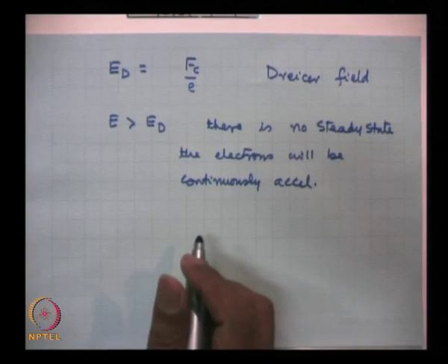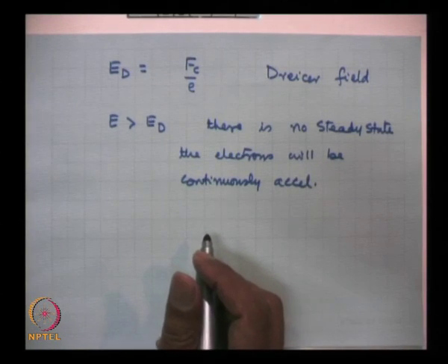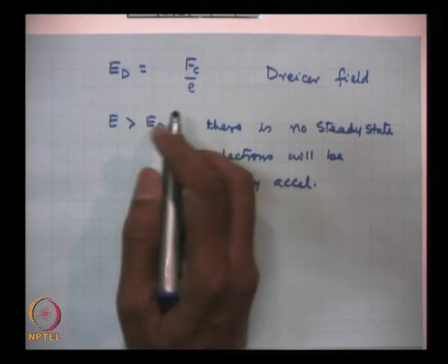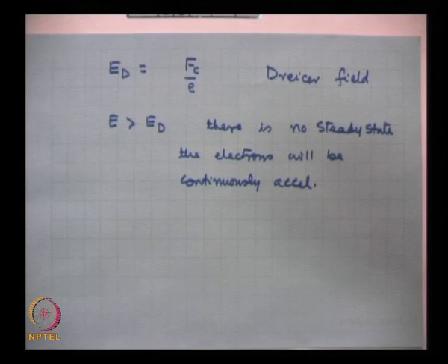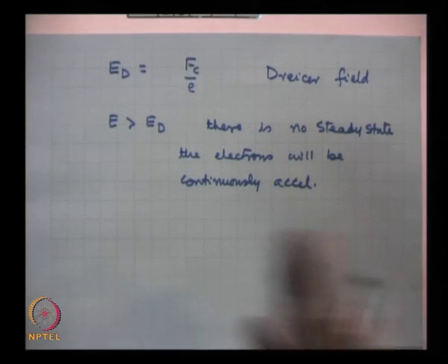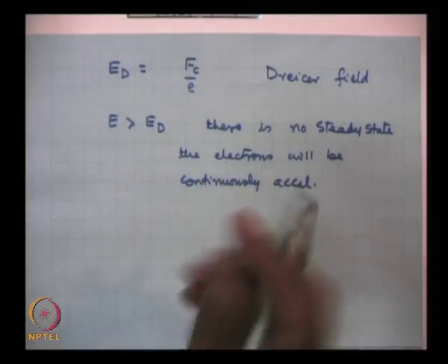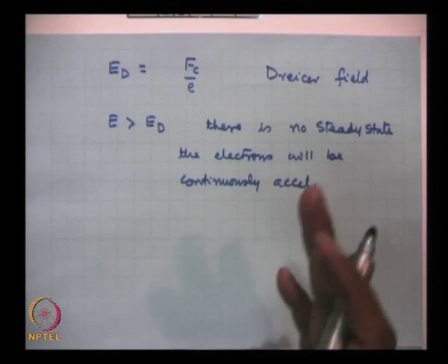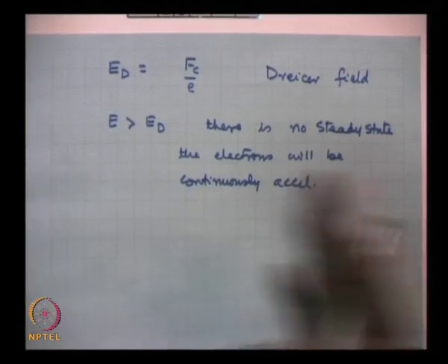Well, this phenomenon has been observed. However, such high electric fields are not applied for infinite time or over infinite length. Once the electrons are out of this electric field region, their acceleration stops. So you still get an upper limit on the electron velocities, because either the electric field is switched off or the length over which it acts is limited. So this is what you get.